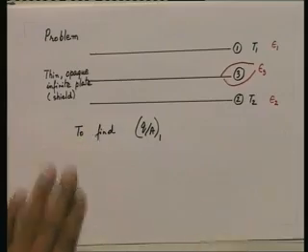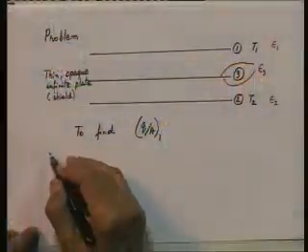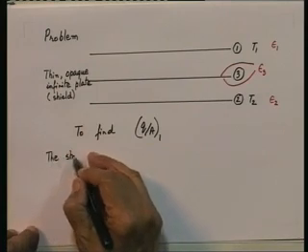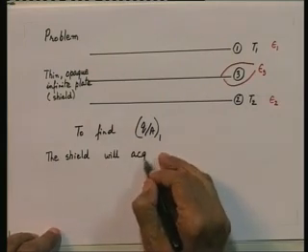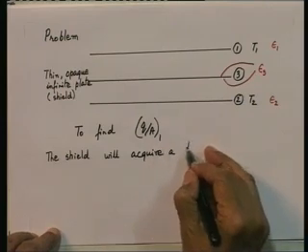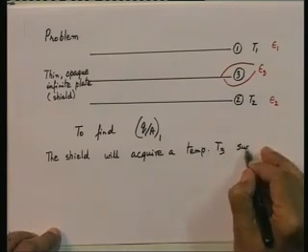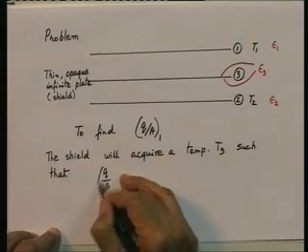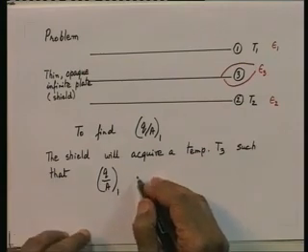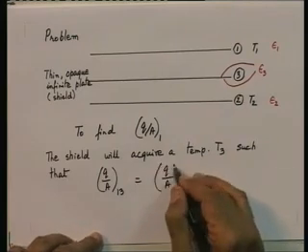It is something between 1 and 2. So, it is like a shield. Now, it is quite obvious that the shield will acquire a temperature T3, such that Q by A 1 to 3 will be equal to Q by A 3 to 2.